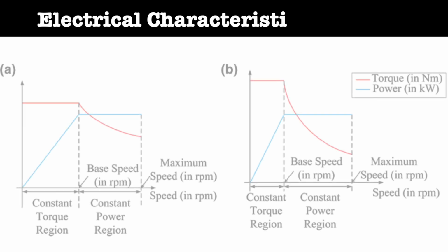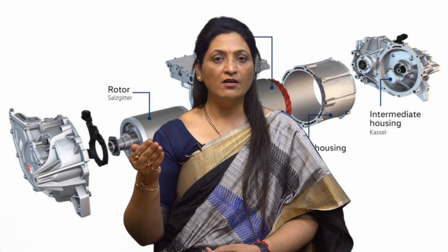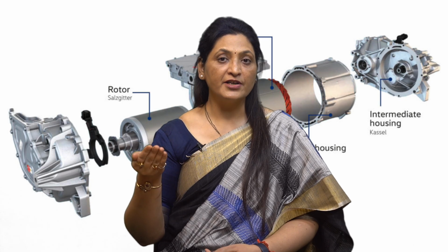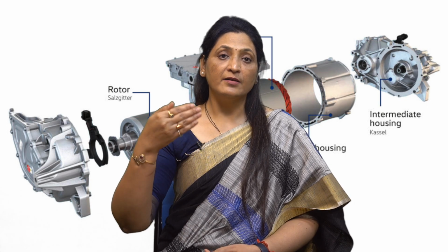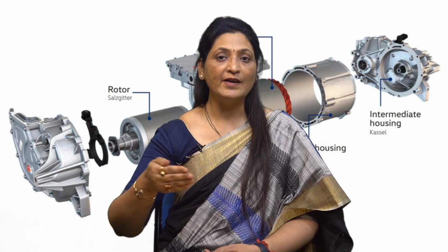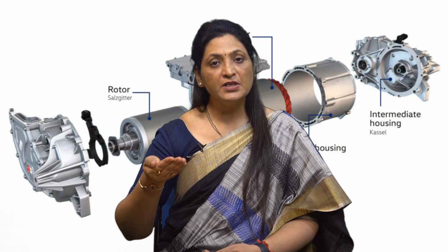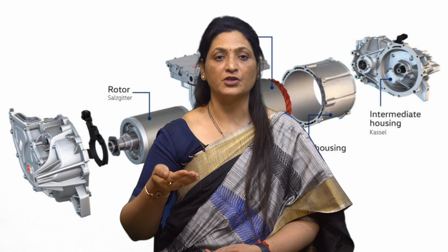Coming to the fourth point, the electrical characteristics of motors such as starting characteristic, running characteristic, speed control, braking characteristics are also considered for the selection of the motor. Also, the size and rating of the motor is important and has to be considered. That is, whether the motor is to run continuously, intermittently or on a variable load cycle, whether the overload capacity and pull-out torque are sufficient.